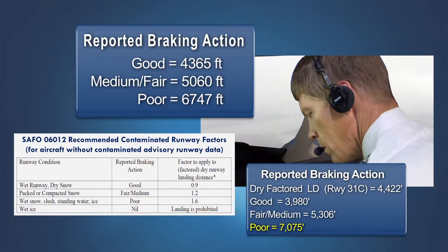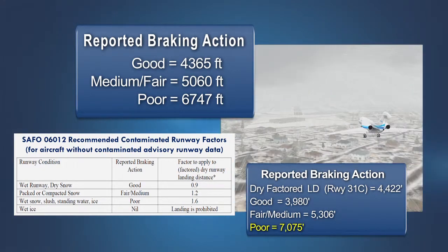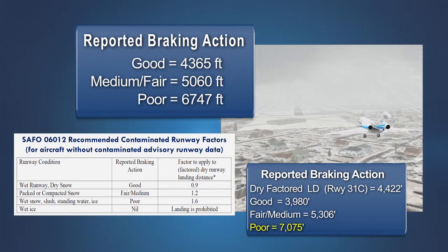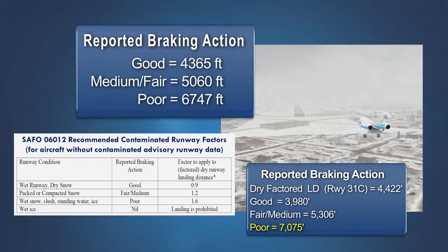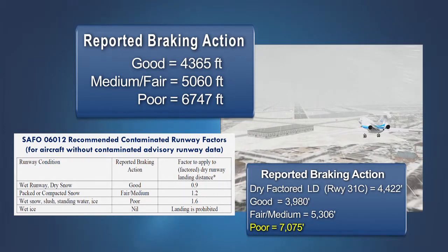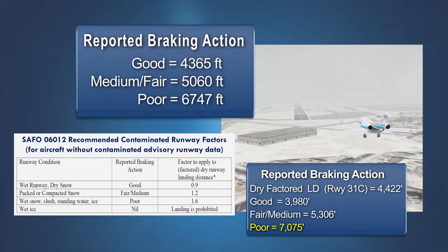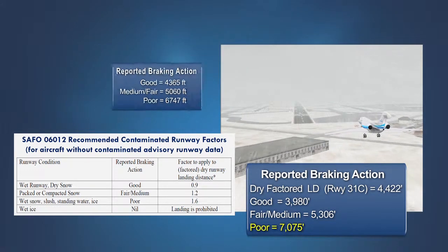The receipt of new or updated information on runway conditions may result in the reevaluation of a previous decision to land. In a case where uncertainty of landing distance remains, it may be appropriate for the pilot monitoring to quickly reference the QRH or TAB data, or in other cases, the prudent use of a go-around and a holding pattern at a safe altitude to reevaluate the decision to land or divert may be the best decision.